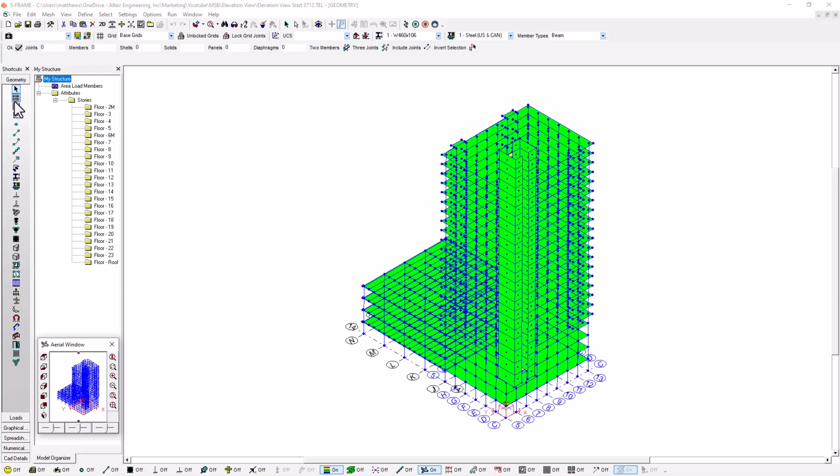And to utilize this, I just click on the elevation tool at the top of the geometry window, and I can choose from different grids that are available in my model. So I can go with the parent base grid or one of the children base grids or one of the existing construction grids as well. And for this example here, I'll just stick with the base grids where we can select a frame from this base grid.